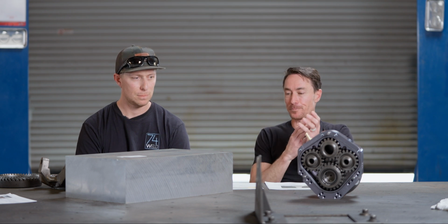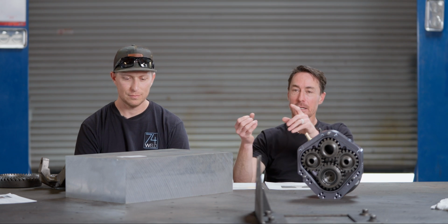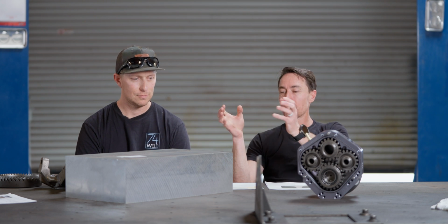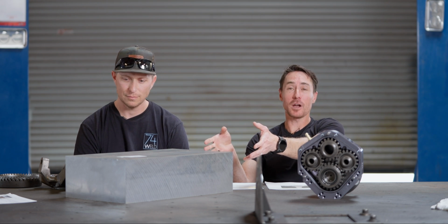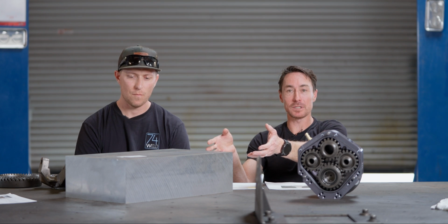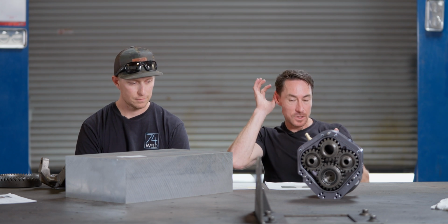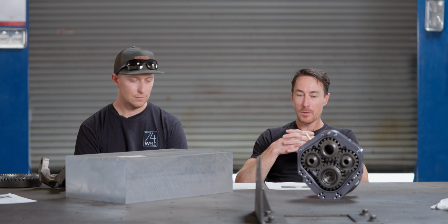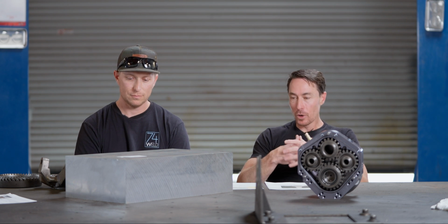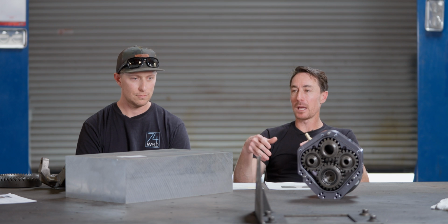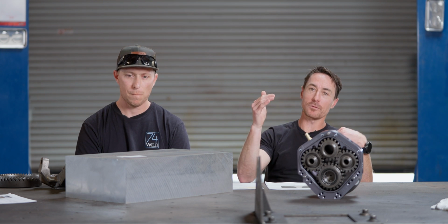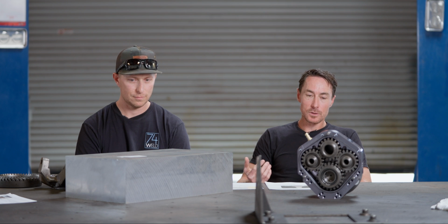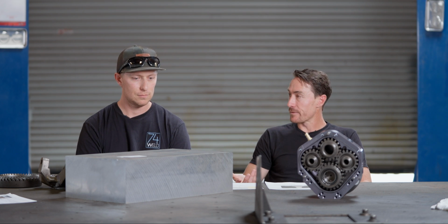And so the downside of this is it's costly to produce, it's costly to purchase, and we have a finished upright somewhere in there. We just have to remove all the material to get to it. Yeah. And so it's admittedly not the best process, but to go to a forging, you have to have dies made, you have to have a certain threshold of volume. It's very expensive. Yeah. To move our product line to a forging will cost hundreds of thousands of dollars.